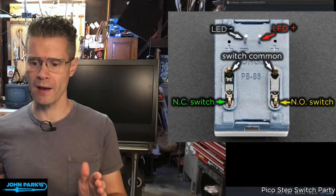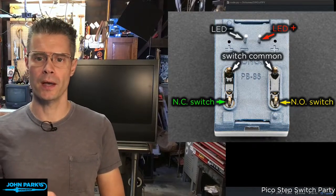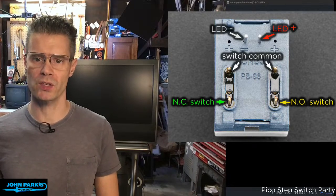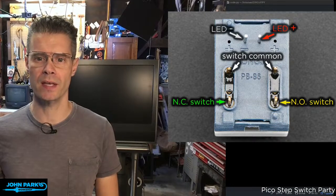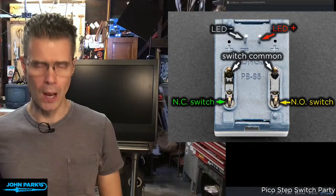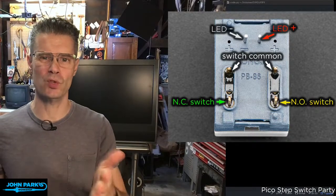First of all, you have your LED there, and the LED has negative marked on it. You'll see in the molding there it says minus. That's the negative leg of the LED. That'll let you know how to wire that up, even though the legs are cut the same length. You essentially want to give that close to 2 volts.